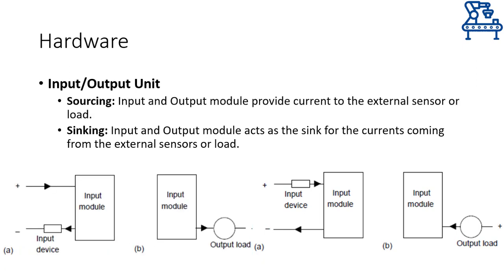Normally, manufacturers from USA, Taiwan, Japan, etc. prefer sinking configurations and hence provide sinking modules with their PLCs, whereas those from Britain and most of Europe prefer sourcing modules with their PLCs. However, nowadays a number of major PLC suppliers like Siemens, Mitsubishi, Allen Bradley all provide both kinds of modules. Therefore, you can choose the one that suits your wiring conditions.